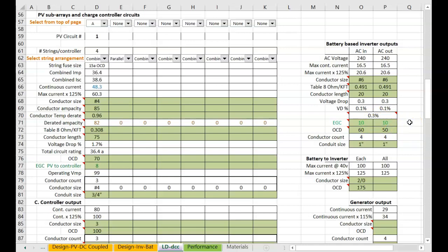But I've seen it where it got high enough that it would actually cause a voltage collapse, voltage drop, whenever some loads would start up. And this is always after hours, non-solar hours, whenever the grid was supplying everything. So look out for that.